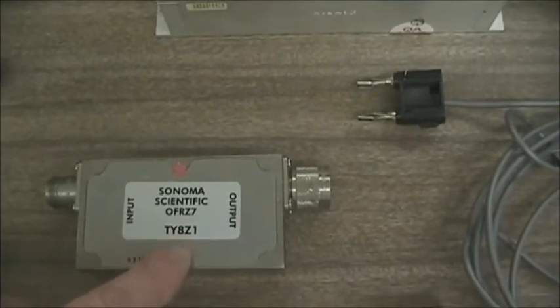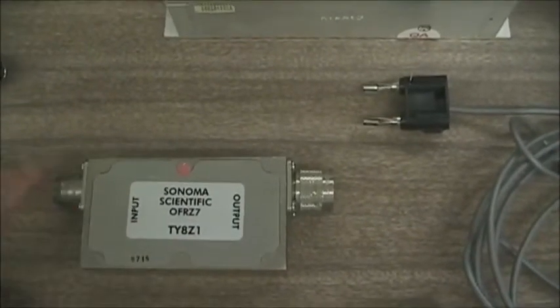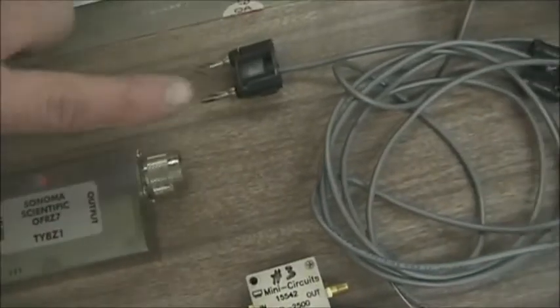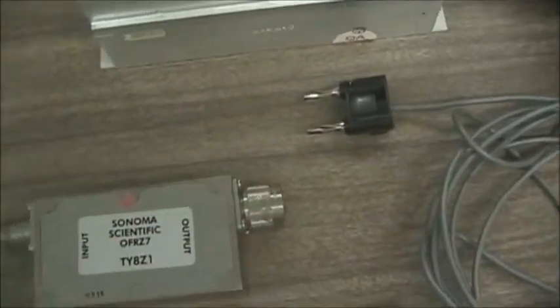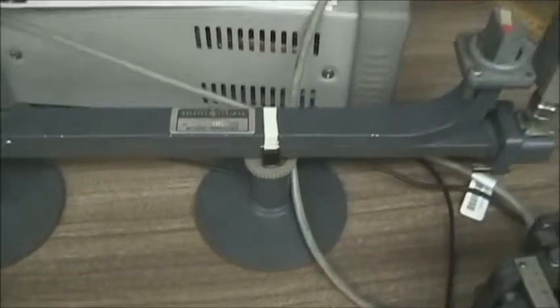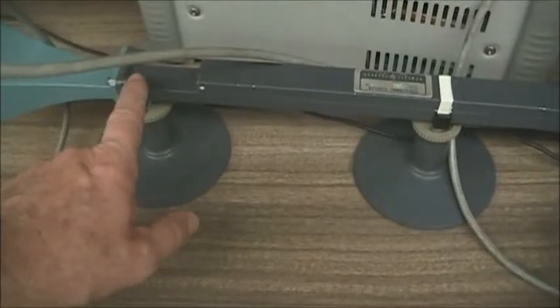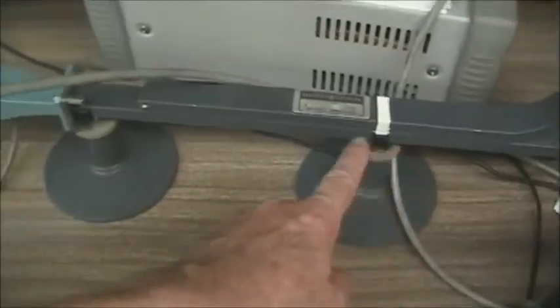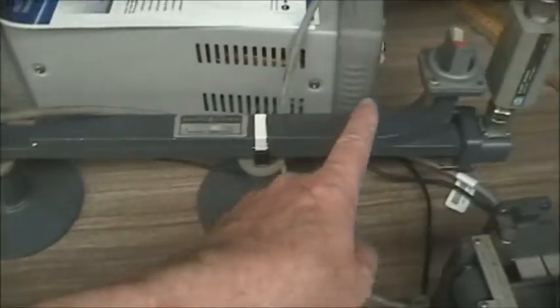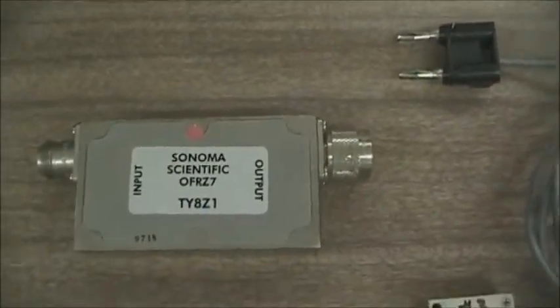Inside it's actually got an extra termination port, which allows the signal to go this way, but no reflection to come back. It's actually very similar to the directional coupler we talked about in waveguide. Signal, in this case, can come from one end, but the return signal goes a different path. In the isolator, it's terminated.